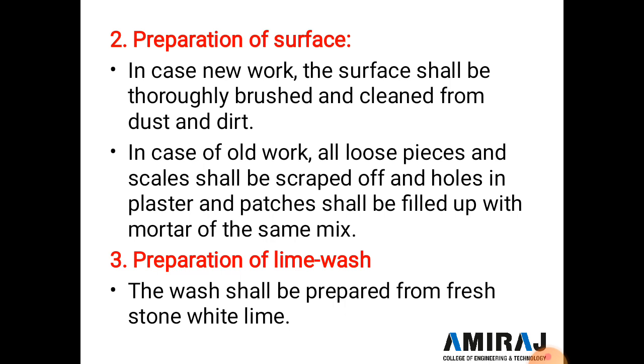Now the second specification for whitewashing is preparation of the surface. In the case of new work, the surface shall be thoroughly brushed and cleaned of dust and dirt. In the case of old work, all the loose pieces and scales shall be scraped off, and holes in the plaster and patches shall be filled with mortar or another material.